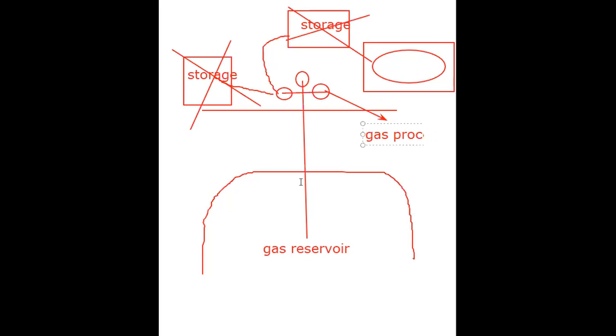So when you go to the oil and gas field, the first thing you should look at is the composition, what you are exactly getting out of the reservoir. Whether it's water, for example, now this is a gas reservoir with water support. It is supported by water, which means it has water underneath it. If the water is also coming out, you now have to dispose of the produced water, and this produced water is toxic. So you need to look at what kind of fluids are coming out. You design your surface facility based on the fluid composition you are getting. That's the whole idea of the reservoir fluid properties.